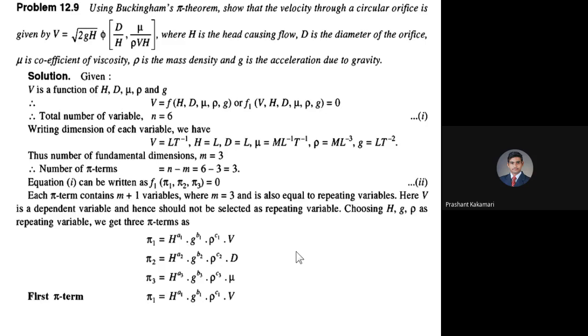Next is the fluid property. We were talking about fluid property, that is the last type. That is density as well as viscosity. Both we have in this problem, mass density and viscosity. So I have already told you, consider the minimum number of fundamental quantities and the raised powers should be less. Comparing mu and density, you can choose mu also, not an issue, rho also, but comparing both these variables, rho has very few fundamental quantities, M L raised to minus 3, and comparing powers, viscosity is having less powers.